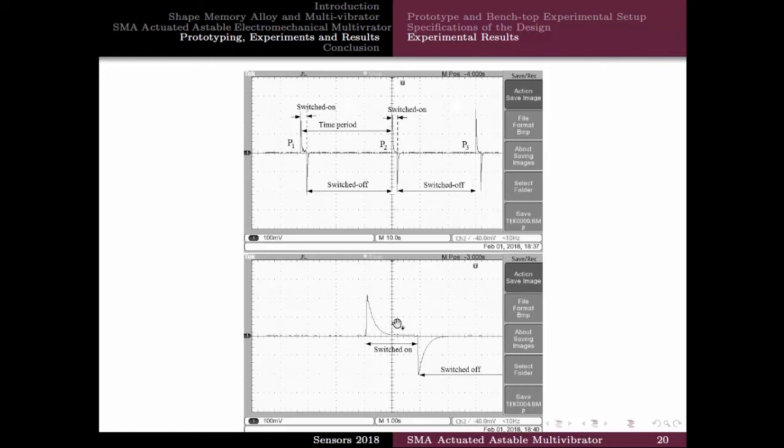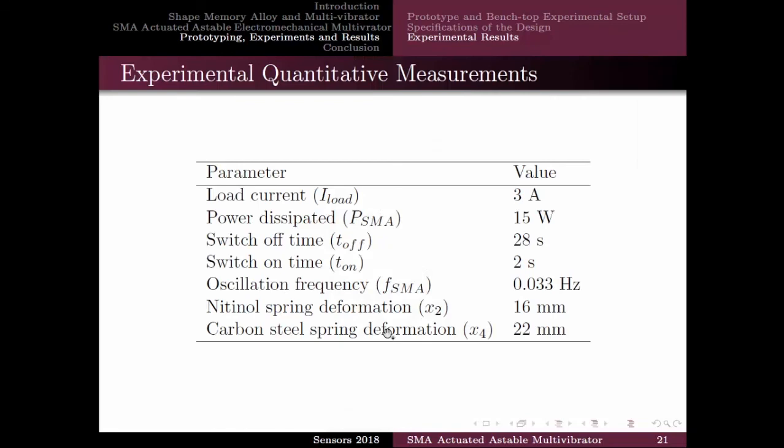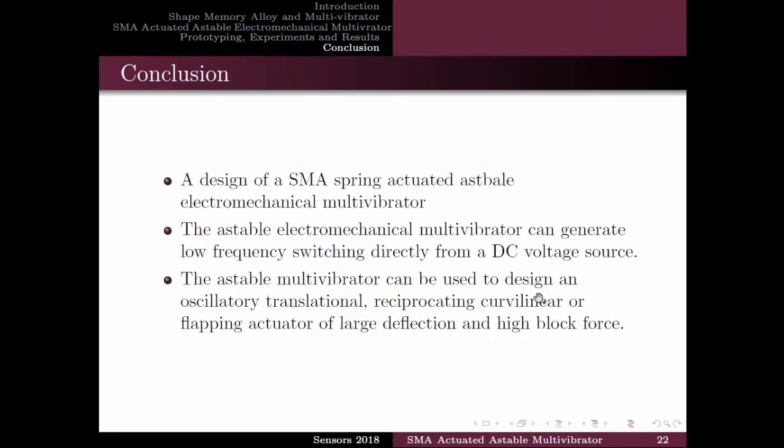Now the shape memory alloy is a spring. As a spring, it can be modeled as an inductor and a resistor in series. Because of that, it has this type of exponential relation. And finally, this is the output result from this one. Basically, it's a low frequency application, so the frequency is very low. But if we bias this one with two shape memory alloy springs, instead of one elastic spring and another shape memory alloy, we'll get a better response.